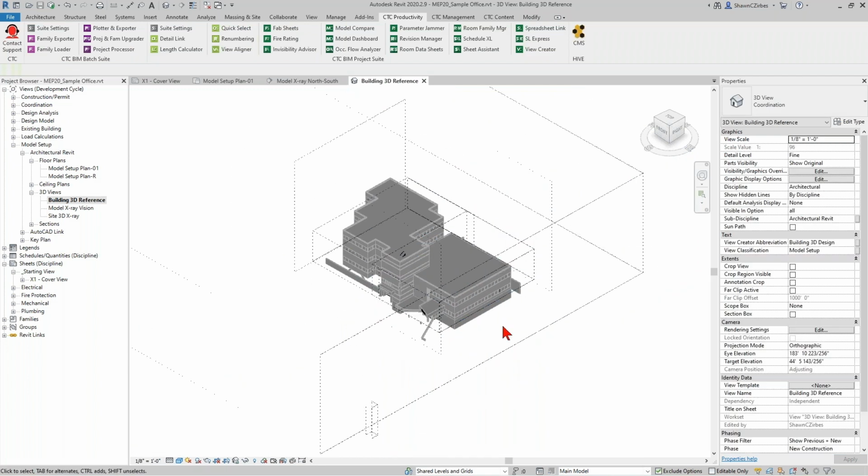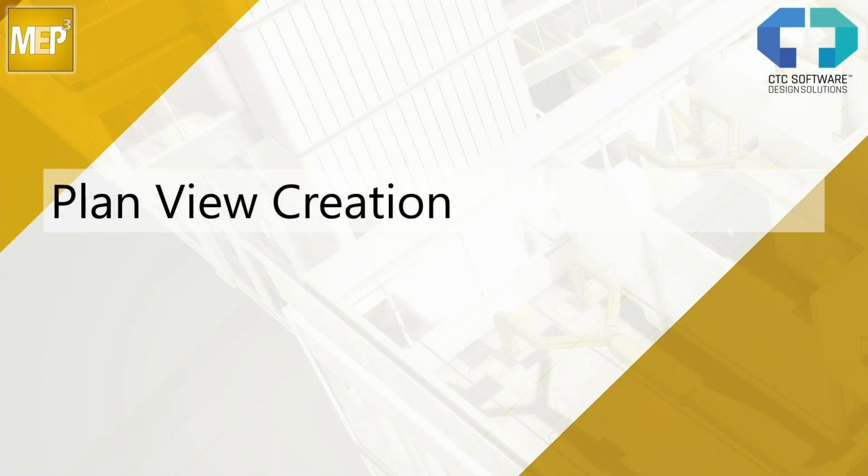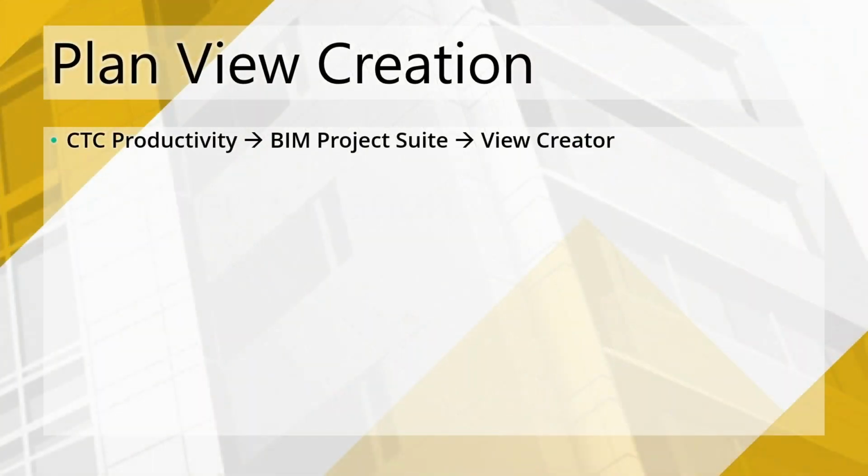All right. Now that I have the architect's scope boxes exactly copied, however it is they've defined them, I'm ready to move on to the next step, which is plan view creation. Now, when you're creating plan views, let's just kind of talk about this workflow real quick. You're going to be using basically the CTC productivity tool, BIM Project Suite, the view creator tool.